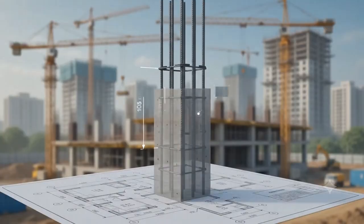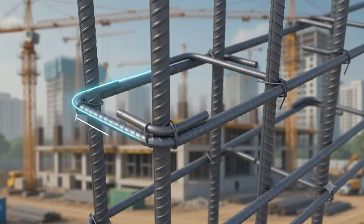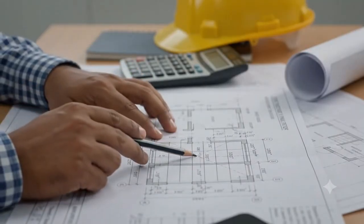Let's calculate steel bars. Step 1. Find the cutting length of main bars. Step 2. Determine the number of bars. Step 3. Find the cutting length of stirrups. Step 4. Calculate total steel quantity. Step 5. Multiply total length by unit weight to obtain the steel weight in kilograms.